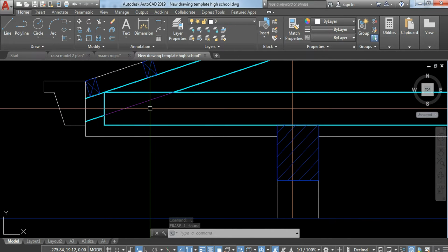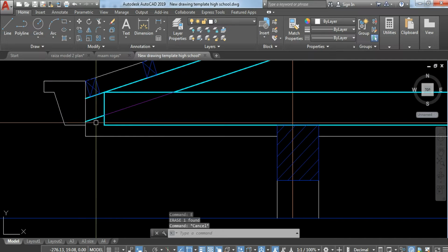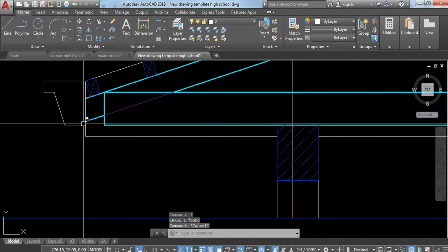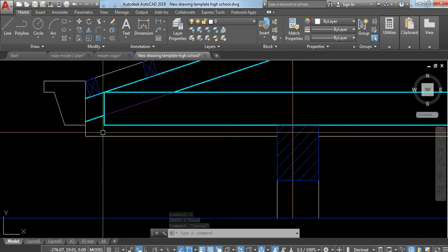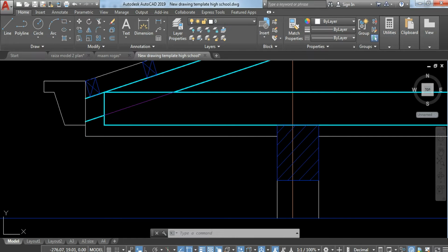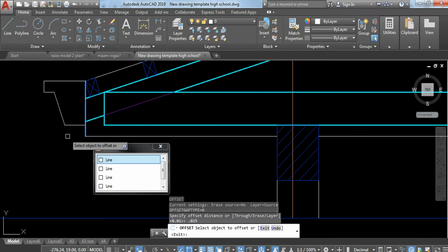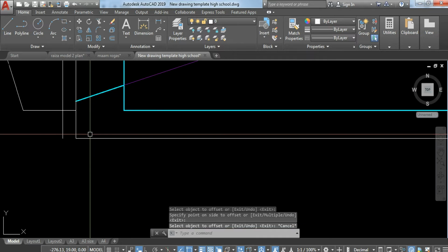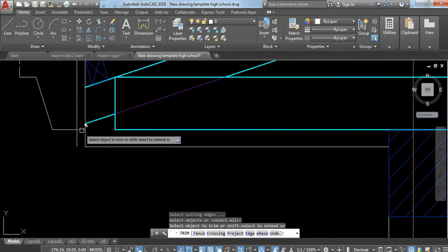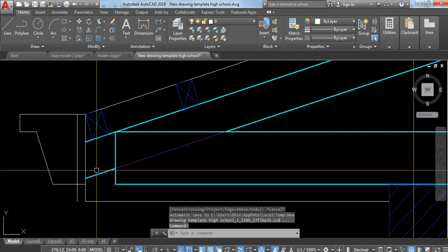So also, you have to remember, okay, position of your what we call the fascia board. So offset ng 0.025 somewhere here. I'm going to extend it a little bit outwards. Palabas for our. Okay, either you can offset it going inwards, you may do so also the same.